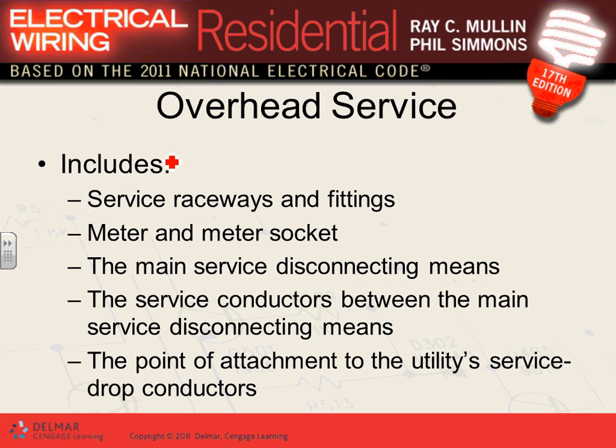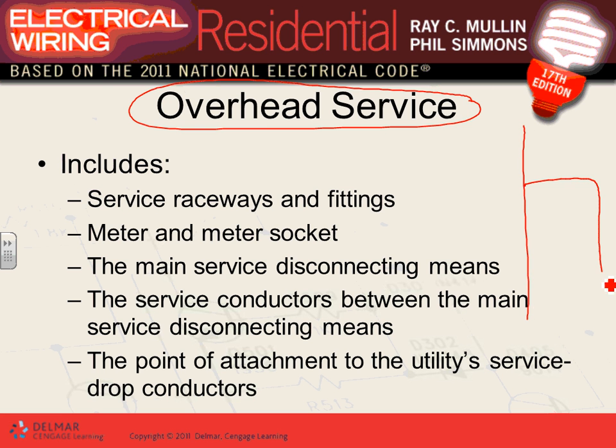If you have an overhead service, which most of residential do, here's my overhead, here's my building. You guys see the power lines coming in here, right? Tying right here. My service point is right at this point. And you're coming in here into a circuit breaker inside the building. You tie at the top, right? That's called service point. So first you have your service raceways and fittings.